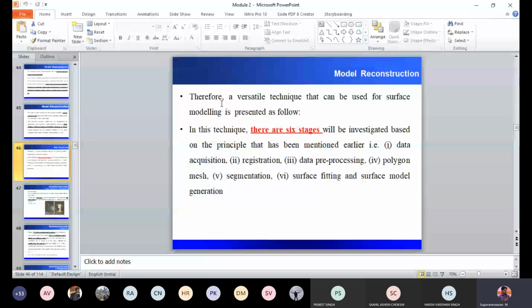Forward modeling is the process which you follow in CAD software. In any CAD software, using a dimension, you create a CAD model, right? In reverse engineering, from physical data, you'll be creating a CAD model. And most additive manufacturing processes take data from reverse engineering, because we are going to work on complex regions, complex features. So in that case, reverse engineering is very much useful.